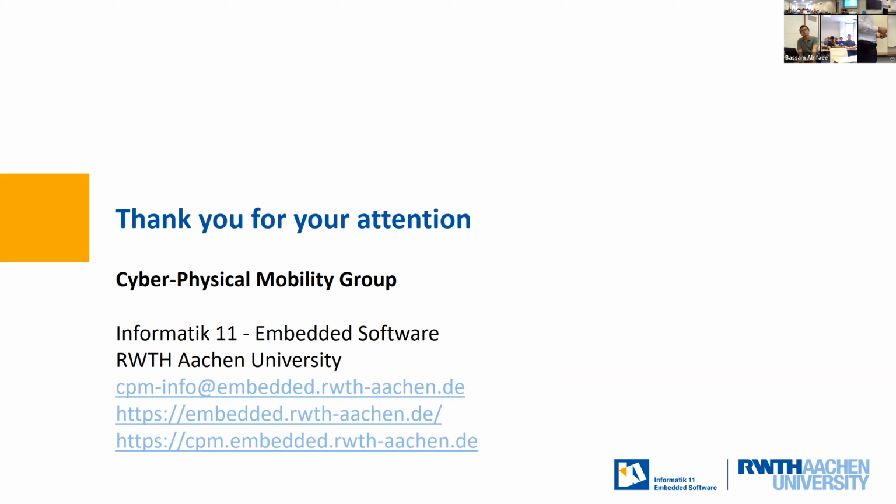And in our implementation of the distributed MPC, we could solve it on NUCs. Intel NUCs, maybe you know these, small computers. Within several hundred milliseconds, I don't remember exactly, something between 200 and 400 milliseconds. And people say for autonomous driving, you should have 200 milliseconds sample time and a prediction of 10 seconds.